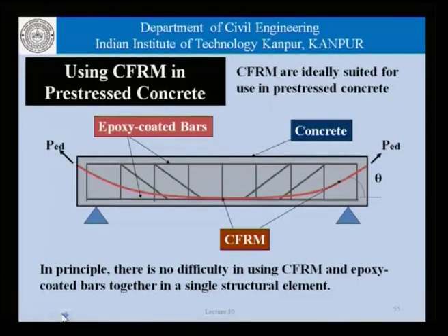And given their high strength, the CFRM are an ideal material for use in pre-stressed concrete as is shown here. So, this tendon here, which is going to be used for pre-stressing, could be a CFRM, and the other reinforcement be simple epoxy coated bars or normal bars, whatever we want.